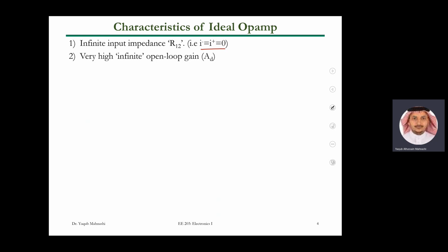Then I ask you, guys, if this AD equals 100K volts per volt, because this is voltage gain. And by the way, this is a real number. Your 741 is the cheapest and most widely used op-amp. It has that amount of gain, and it can be higher. So in that case, can I say I will see 100K volts at the output? You cannot, right? What will it say, guys?